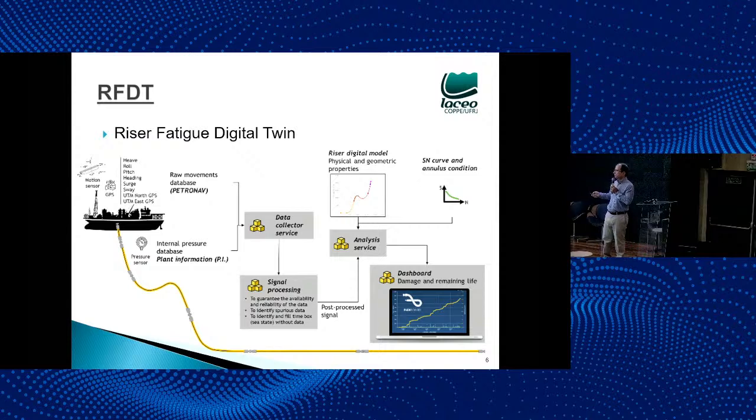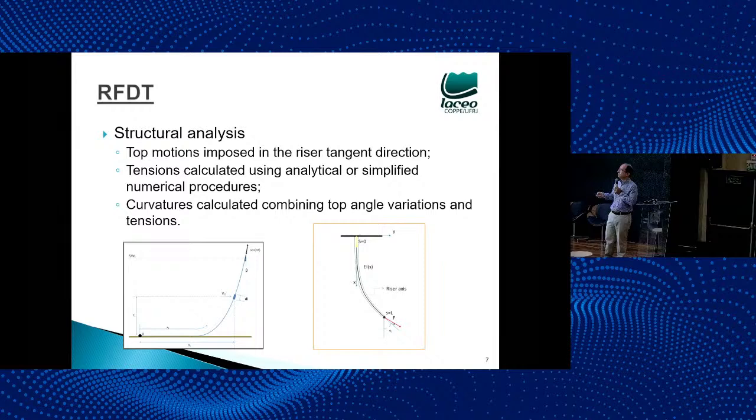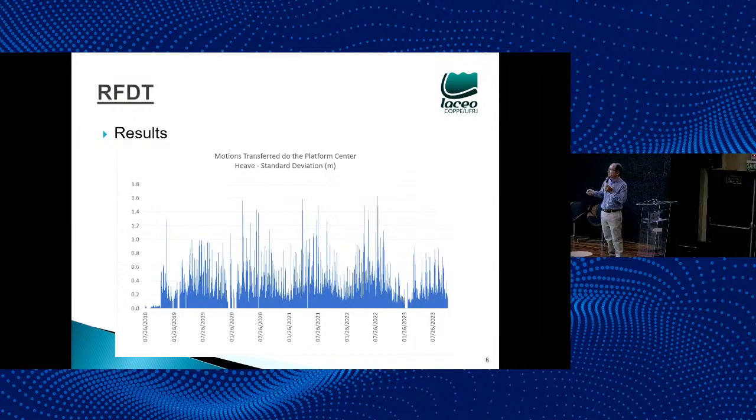And the results this kind of application gets is basically to evaluate these top motions, so we can compare the long-term statistics of motions really measured at the platform with values that we use at projects, the design criteria that we use in the projects to determine if our previous considerations were too conservative or not.